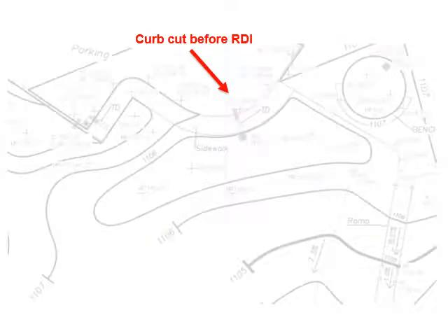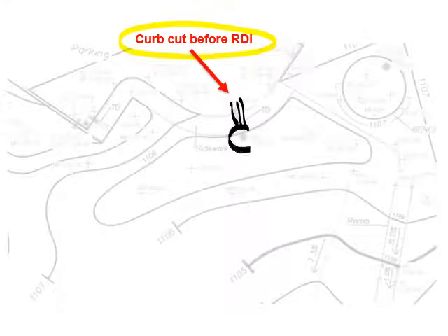And of course, this curb cut has to be in front of the raised drop inlet. So our curb cut will be right here, and then our raised drop inlet is going to be right after that. The reason is that we want the water, once this fills up with the dirty water, we want the clean water to flow into the...